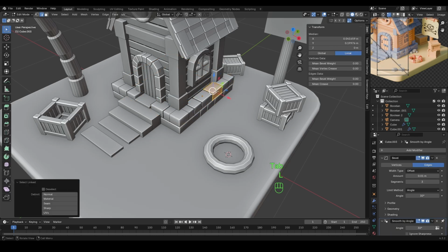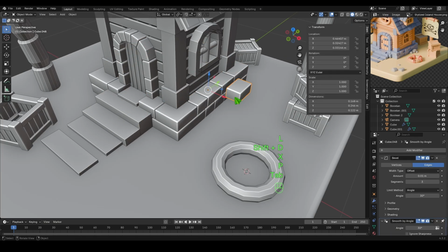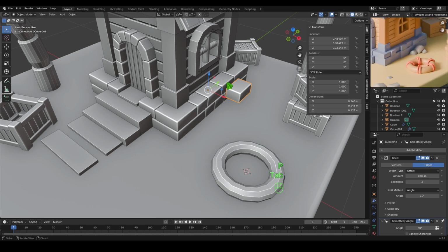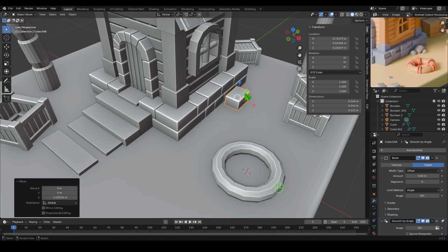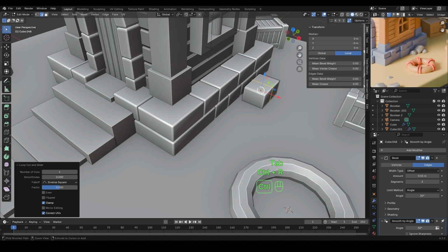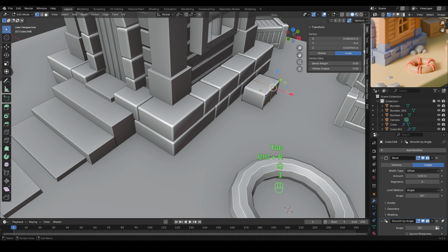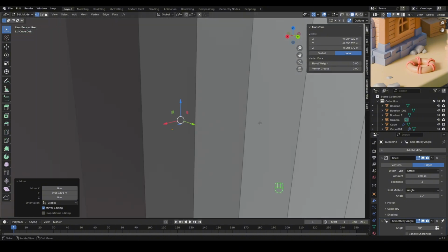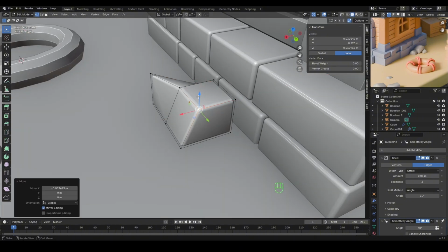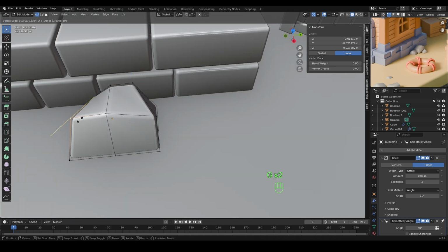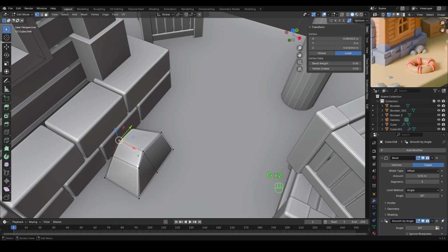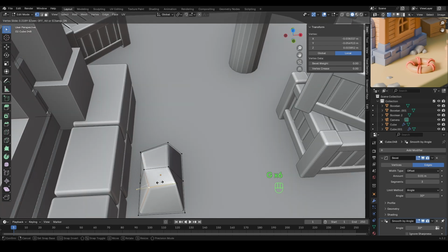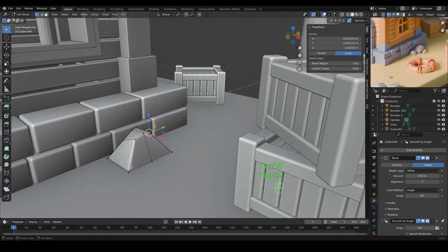Let's select this. Shift D to duplicate, P to separate. And let's right click, set origin here and let's go to edit mode, select them. Move it here, move it down, move it here. We can make a rock like that. Easy peasy. And move it here, down, down, down. Like this. Easily we make some rock shape.